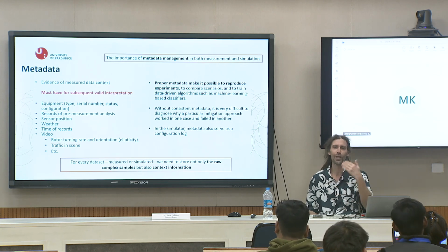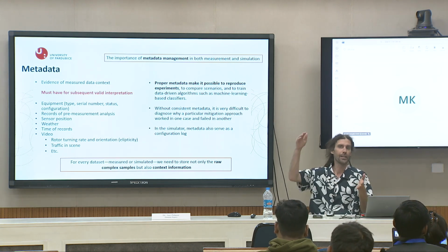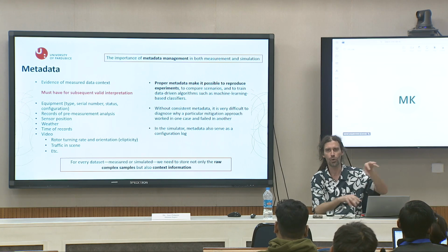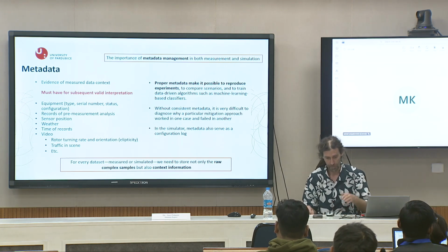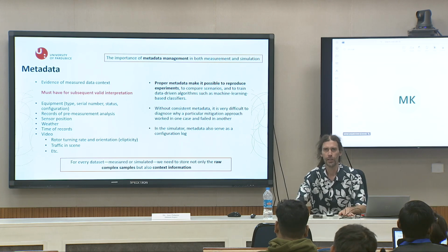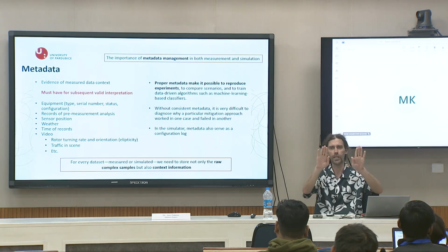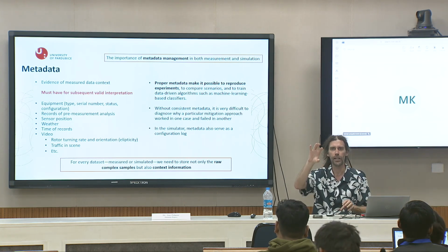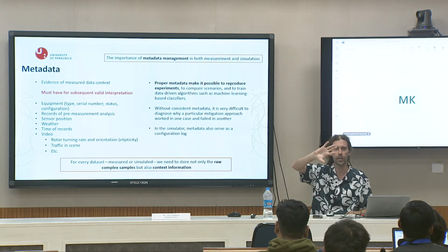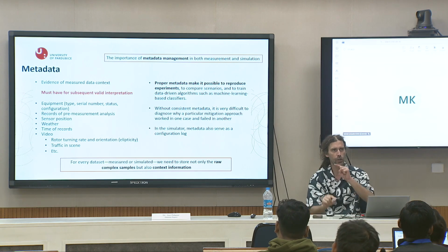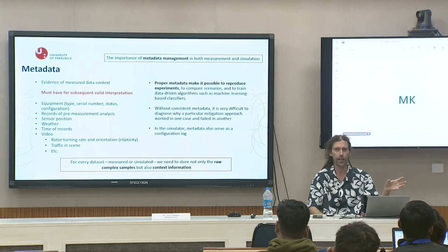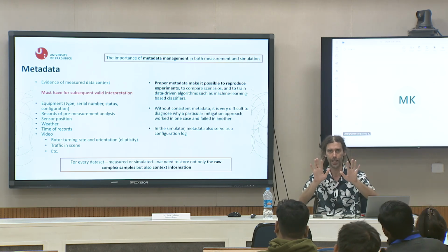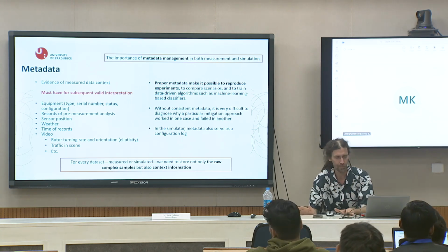From one rotation you get a lot of information: speed, and the type of wind turbine you already know, so you can put all this information into your model. Then you compare the measurement and your model results, and they will be almost the same. And what is the advantage? You know the setting of the model, and now I can change just the initial angle or rotation speed, and even if I don't have a measurement for this different setting, I know it is valid because the setting was already set once and confirmed. And this is really important.